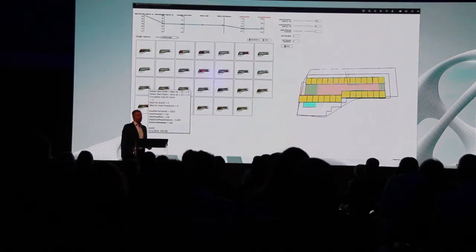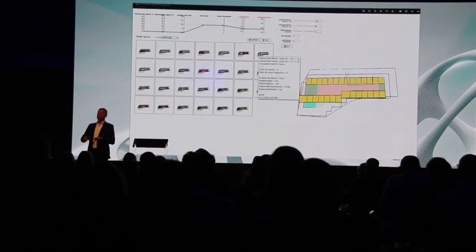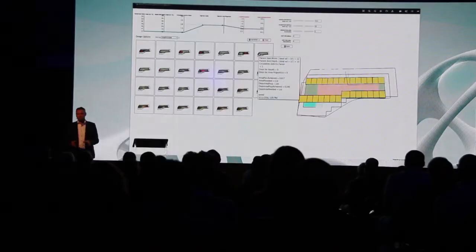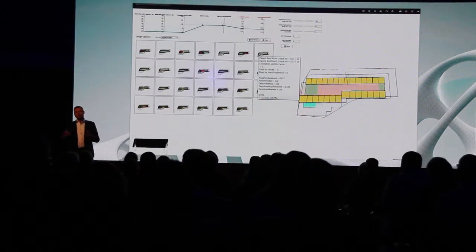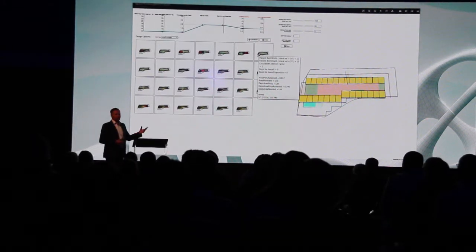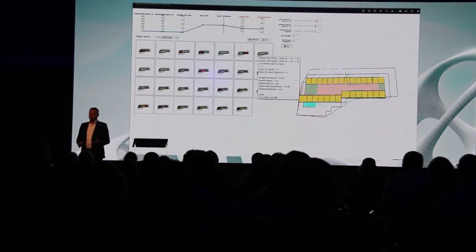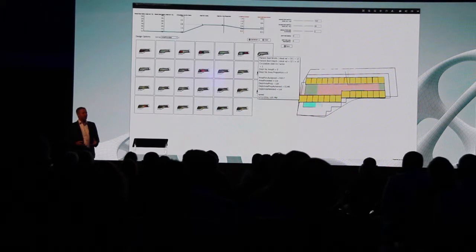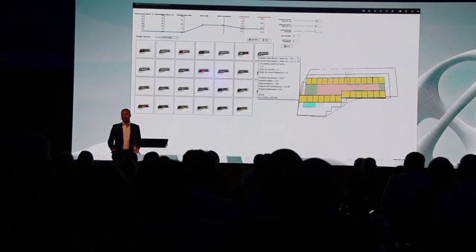What you can see in here is that the feedback you get from Fractal can be anything, because you own it. You own the whole analysis within Dynamo. You set up what you want as what we call a watch result, and you name it as you want. It appears in that parallel coordinate diagram. The inputs are also something that you choose, how to drive this whole design. So it's not Fractal deciding for you how it should look. You can completely customize it in your own way and make your own analysis for it.